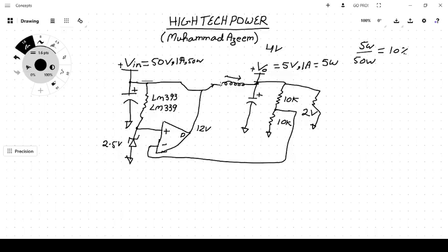In this case it will start increasing the voltage across it, which would be reflected to the whole path, and so the voltage across the transistor would also increase, and because it is in the off state, that increased voltage would go beyond the breakdown voltage of the transistor, and it would be destroyed.